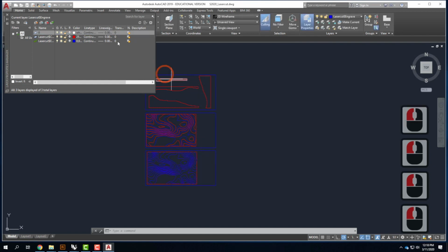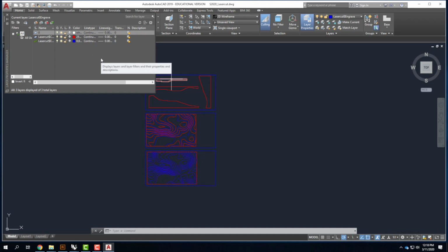An important note about the laser cut: when you go to do the laser cut, make sure that you're printing at full scale. Don't scale the drawing, don't scale the fit. It's okay, the border on the outside is going to get cut off. Just don't scale the fit, because otherwise your steps aren't going to be the right sizes. So we want to make sure that they are in fact the right size when you go to do the print. If you have one of the lab techs help you do it, make sure they don't scale the fit because it does make a difference.